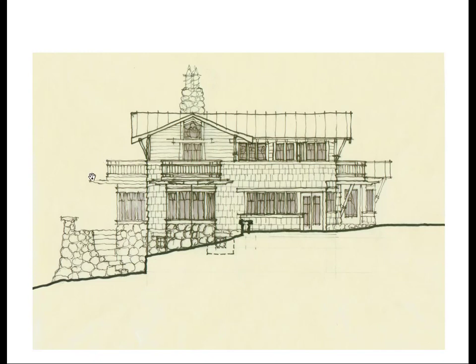Okay, so the closest objects are going to gain your thickest line weights, and the furthest away objects are going to gain the thinner line weights. And then finer details like the shingles, the rock in the background, and the hand railings will also get a very thin line weight.